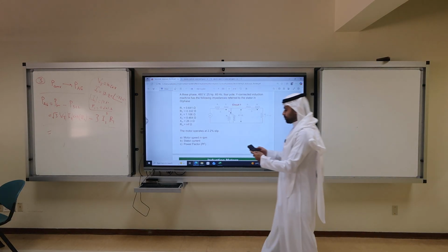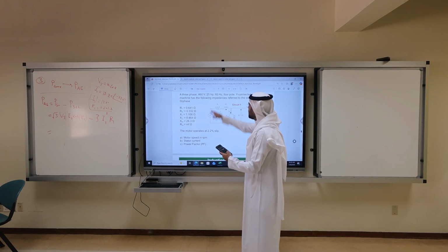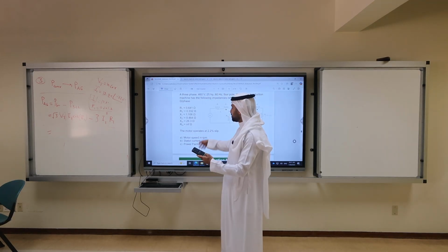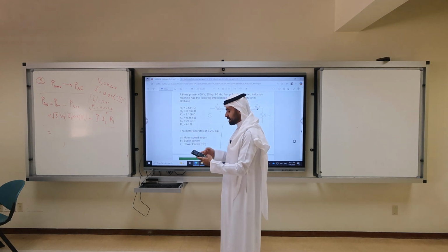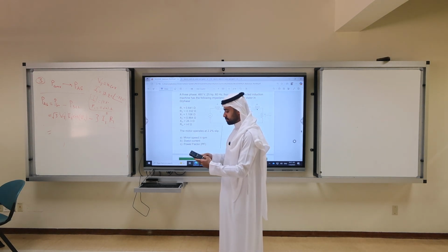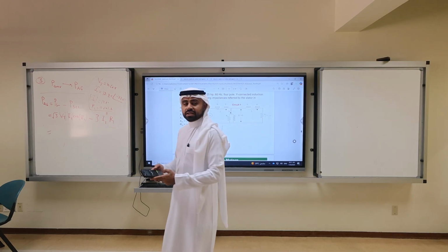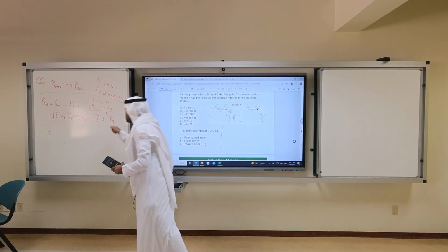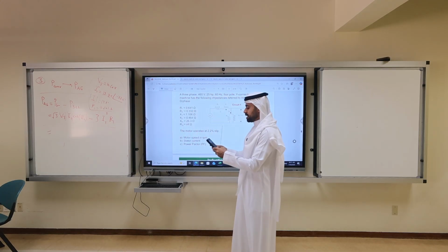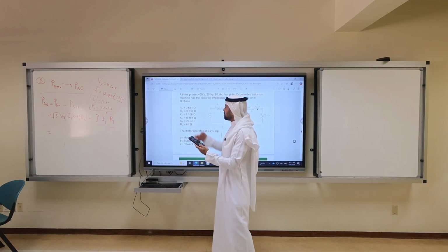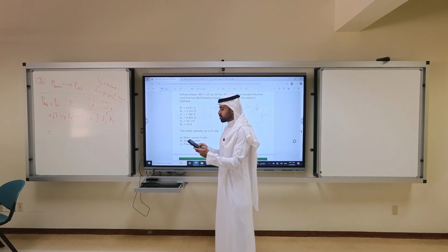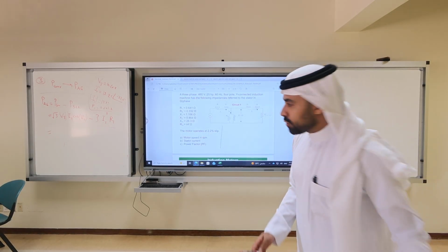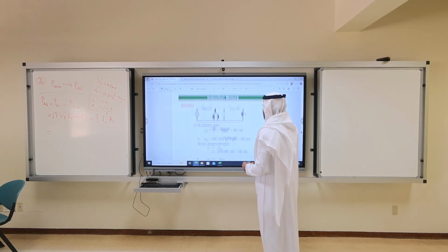Square root of 3 times VT times I1, 18.88, times the power factor. What was the power factor? 0.833, right? The input power is 12530 minus 3 I1 squared R1, 3 times 18.88 squared times R1, 0.641. So you should get 11,844. That's the air gap power.